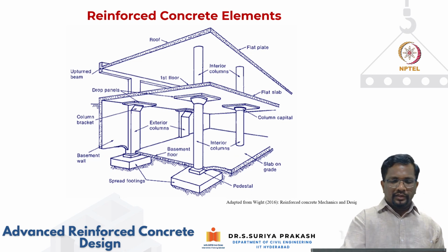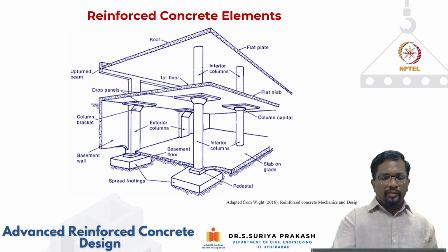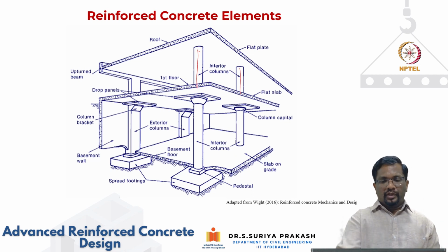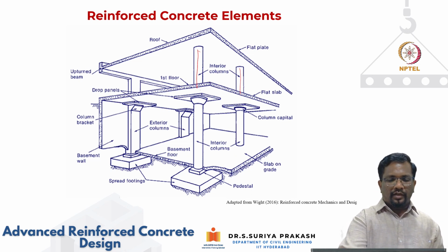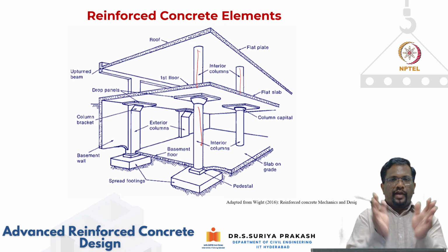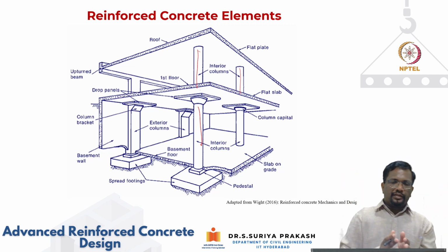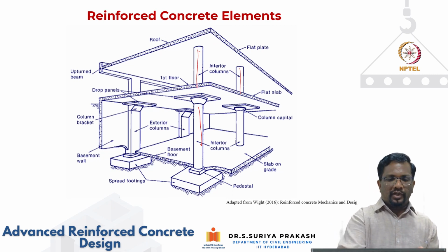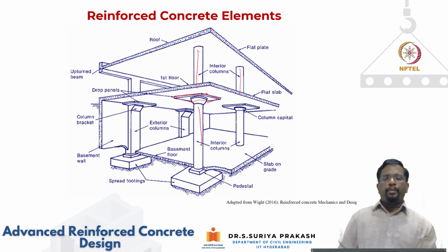You can see here that in this system, we have slab that is directly connected to these columns. Okay, you can also have another variation of this where the slab is again connected to the column here. For example, if you look at it, above the column, what you have is a flaring, increased thickness of the column, which we call a column capital. Then you also have an additional thicker element like this, what you see here, right? So this is called a drop panel.